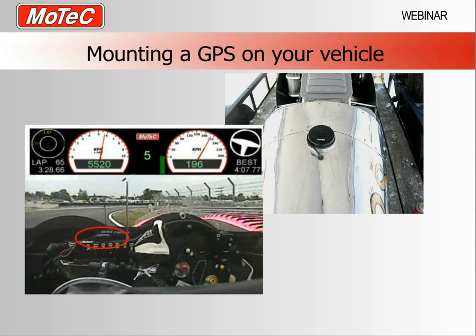Okay, so the thing we're going to talk about next is mounting the GPS on your vehicle. If you can imagine what you do with a normal everyday road car, you just place your GPS on the dash. Now when you look around the sky with your GPS on the dash, it will tell you there's X number, 8, 9, 10, 11 satellites available for you to select from. And when it's only trying to update at 1 Hertz, it can always find a couple of satellites to give you a lock on where your position is on the road.